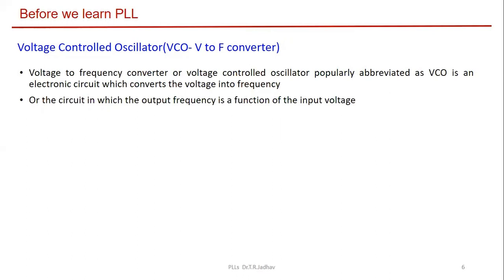Actually, even though we don't give the input, we have a power supply. So we are providing a DC energy through the power supply, and that DC energy gets converted into oscillations, that is AC energy. So although we don't give the input, there is always a conversion of energy and we get the oscillations. So in an oscillator, we say that without any input, we get the output oscillations.